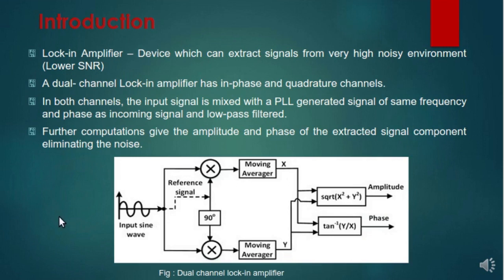We are using a dual channel lock-in amplifier with in-phase and quadrature channels. In both channels, the input signal is mixed with a locally generated signal of the same frequency and phase as the incoming signal, and it is low-pass filtered.